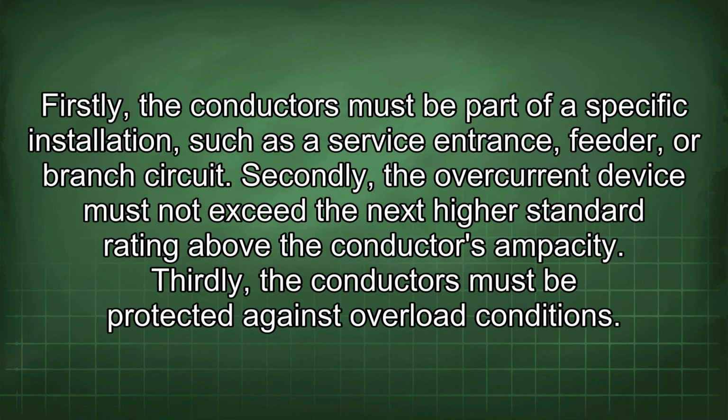Firstly, the conductors must be part of a specific installation, such as a service entrance, feeder, or branch circuit. Secondly, the overcurrent device must not exceed the next higher standard rating above the conductor's ampacity. Thirdly, the conductors must be protected against overload conditions.